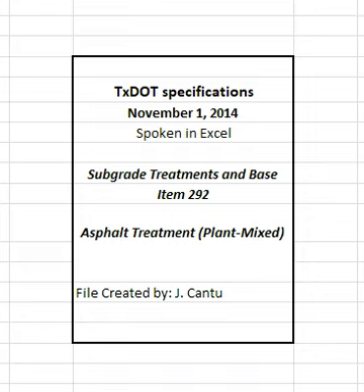Do not use department or contractor-owned RAP contaminated with dirt or other objectionable materials. Do not use department or contractor-owned RAP if the decantation value exceeds 5% and the plasticity index is greater than 8. Test the stockpiled RAP for decantation in accordance with TEX 406A, Part I. Determine the plasticity index in accordance with TEX 106E if the decantation value exceeds 5%.